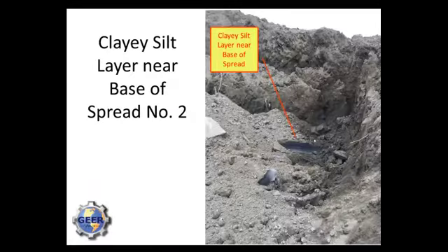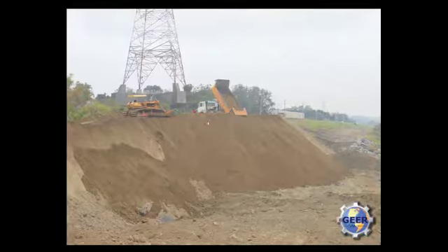And the reason it has liquefaction is because below the liquefiable sand, you have a silty clay layer near the base of the liquefied zone that prohibits water from infiltrating, and this has caused the sand to liquefy at the base of the slope. And this is how they retrofitted the slope. As you can see, they just dumped it and didn't compact it. So will this area liquefy again? I'm pretty sure it will.